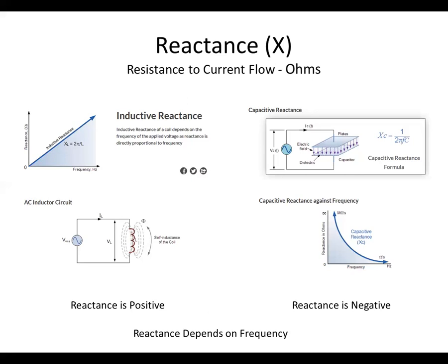So that's what we mean by the reactance. In a resistor, if you pass current through a resistor, the energy is dissipated as heat. But in an inductor, it's just exchanged. It's stored and returned back to the circuit. Stored, returned back. So it'll consume energy by the storage, but it doesn't dissipate it like a resistor does. So as you increase the frequency, the reactance goes up. It has greater and greater resistance to the current flow of an AC signal.